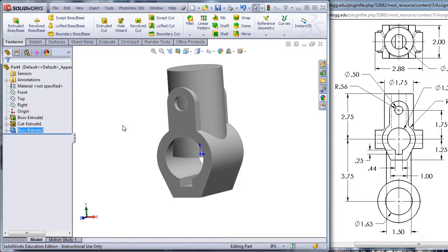So what I'm going to ask you to try and do throughout the semester is to create the solid form first, all of it, and then do all the cuts. This will always keep you out of trouble. It also makes the model easier to edit as you get down the road. So cuts last. But I'm going to go ahead and keep working on this one just for the fun of it.